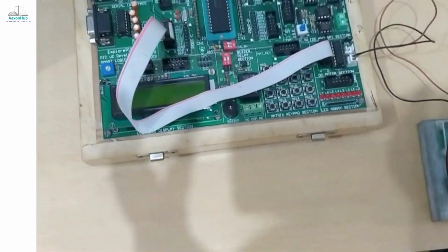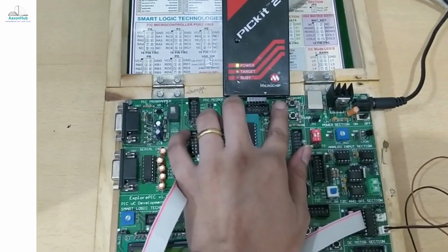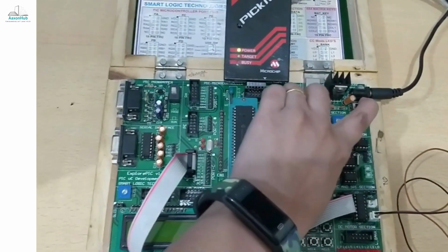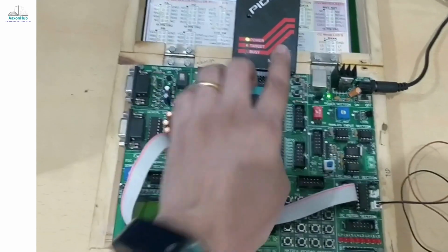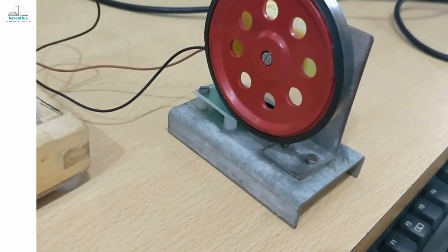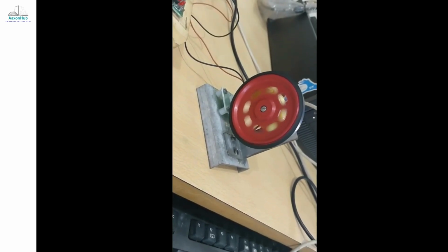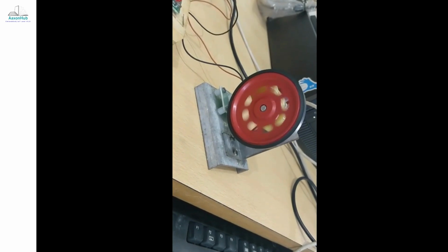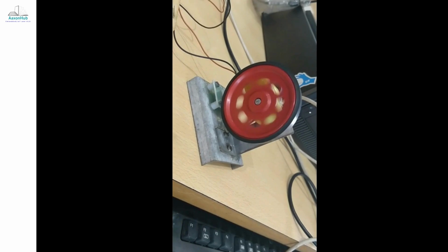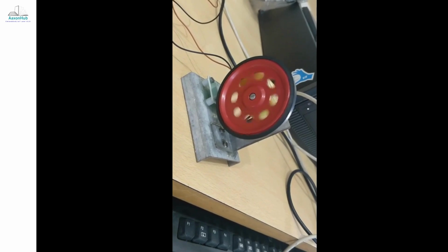Once you successfully download that executable file using PIC18 and MPLAB, just provide reset. The output will be displayed on the DC motor. You have to turn on the supply and you have to reset. We can control it using PWM. If you carefully observe, as and when we change the PWM rate, the speed is getting changed. In this way we can have variable speed for this DC motor using PWM.